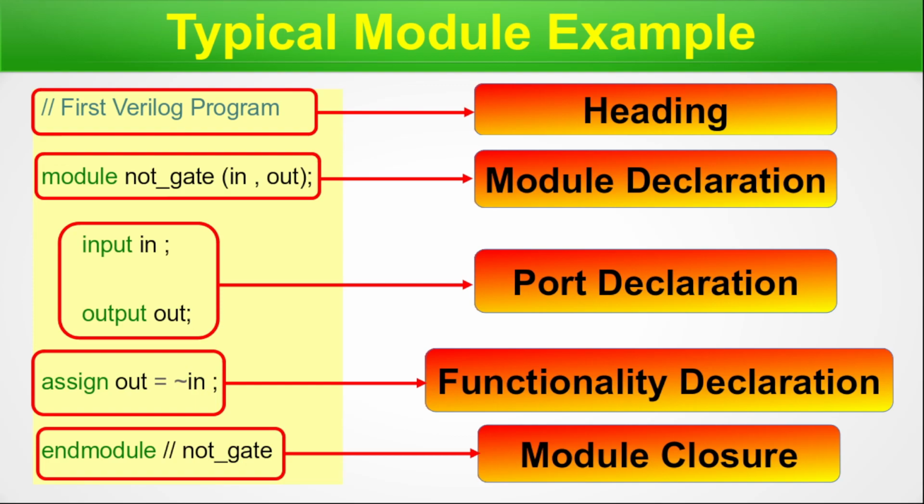In the next episode, we will simulate in an actual Verilog simulator and go through the output. Testbench module example. Whatever module we have written, we have to test whether it performs the intended functionality. That means it's a NOT gate, right? So that NOT operation is happening properly. For that we also have to write a testbench.